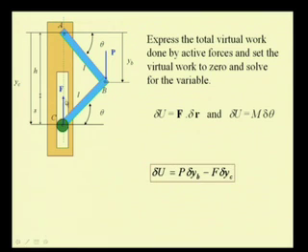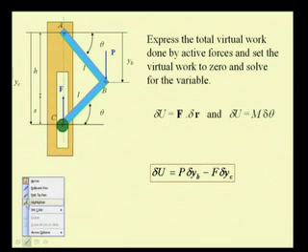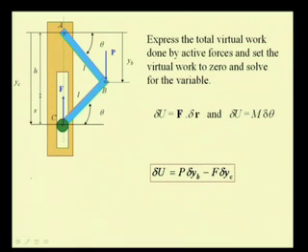So, we have two forces F and P, and we write them. P times delta YB: both are in the same direction, that is this positive virtual displacement of this point B and this force P are in the same direction. So, their work is positive. So, P times delta YB.